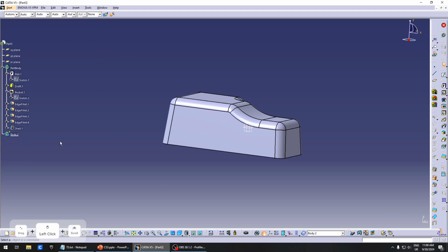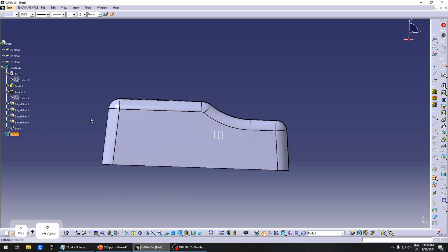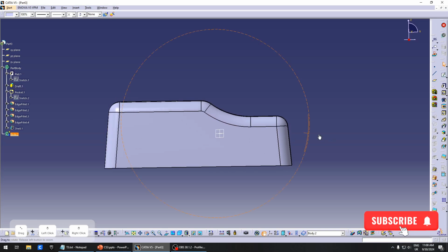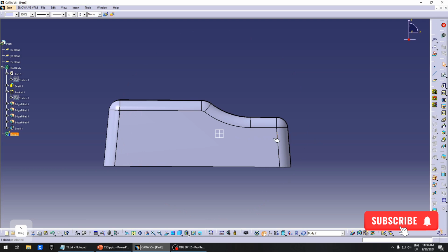Now that we have our base, so to say, for the part, we can go ahead and create a new body. Now this body is the one that will benefit from one of our Boolean commands. One of the use cases I find very interesting for Boolean commands is when you have one feature and you need to multiply it multiple times all over the part. So for this I will try to showcase a different feature as well, which is the shaft command, and we will draw one of those little bumps on the part, and then we will multiply it.